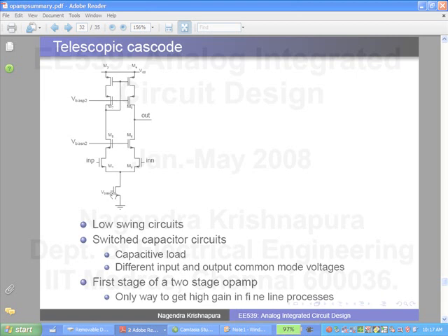No, you can't do that. No, I'm talking about during the design process. I'm not saying that you take a design and then you scale all W's and L's by equal amounts and in the same proportion and get a higher gain with the same operating point. That's usually not possible. What I'm saying is you take the same topology perhaps. Now you increase all the lengths and widths. Perhaps not in the same proportion. You will have to design it. That's part of the design porting process.